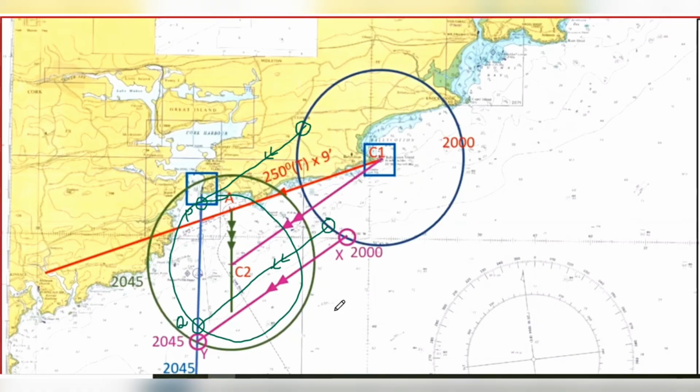Sir, that's absolutely correct in this chart, because it went onto land, so it is not possible. Right. But just hold on, we will go further. So here we have got clarity. Even though the final positions were both in navigable waters, when you go back, you see the CMG running over land and your initial position also coming on land, which is not possible. So it immediately tells us this one is not possible and this one is the correct one. So the first doubt is sorted out. Now let's go further. Now tell me the second doubt.